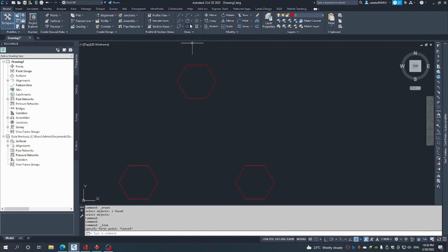So we would come in here and say, if I draw a circle, and it's asking us for the center, we put the calculator function, and we write in an expression that says mid plus mid plus mid divided by 3.